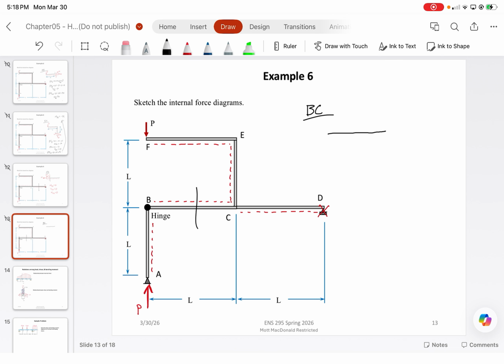It looks a little weird, but if you think about it, rotate the page 180 degrees and just flip it, and you'll see that basically the cut is on the right-hand side with respect to the orientation of the reference fiber. It's a bit confusing, so sometimes you just need to rotate the pages around and follow accordingly. And then the moment, positive-wise, would be this way, so it would be counterclockwise.